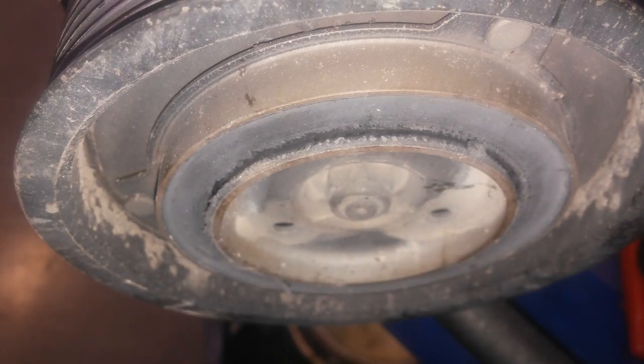Okay, so we had fixed the leak by evacuating the system, replacing the component, and pulling a vacuum on the system to verify no leaks. Then I recharged it with the appropriate amount of refrigerant. Turned the AC system on, still not working. If you look at the center of your compressor while your AC system's on, it should be spinning, but this one is not engaging. So I had to remove the compressor and take a look at it, and this is what I found. The clutch was actually broken, so it needed an AC compressor as well.